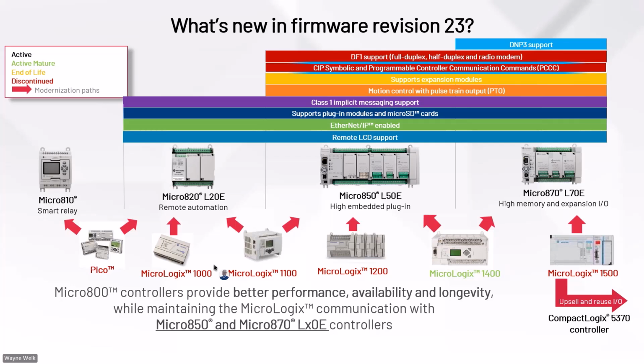We have added new features to the Micro800s. We can now support limited Class 1 messaging. That means we can do some remote IO or put a drive off of a Micro800, which is something you couldn't do with MicroLogix. It's going to have tighter integration. And I think I removed the slide, but there will be a new version of CCW being released probably in the next year. It will not be called CCW. It'll have a look and feel closer to Studio 5000. So just be ready for that.